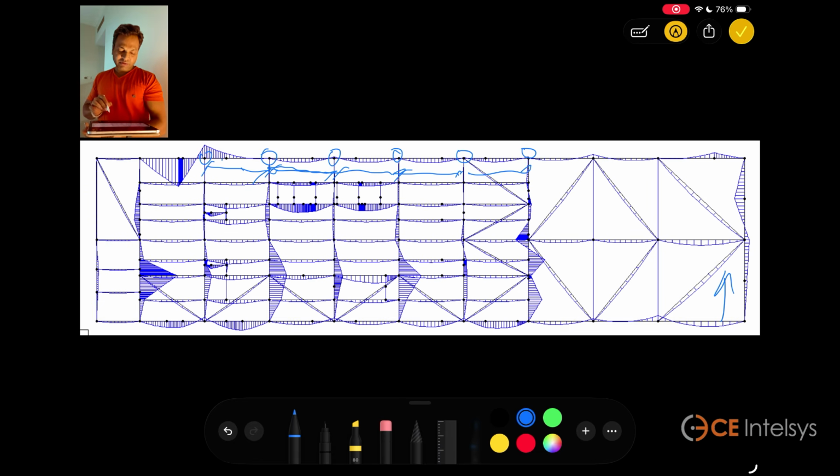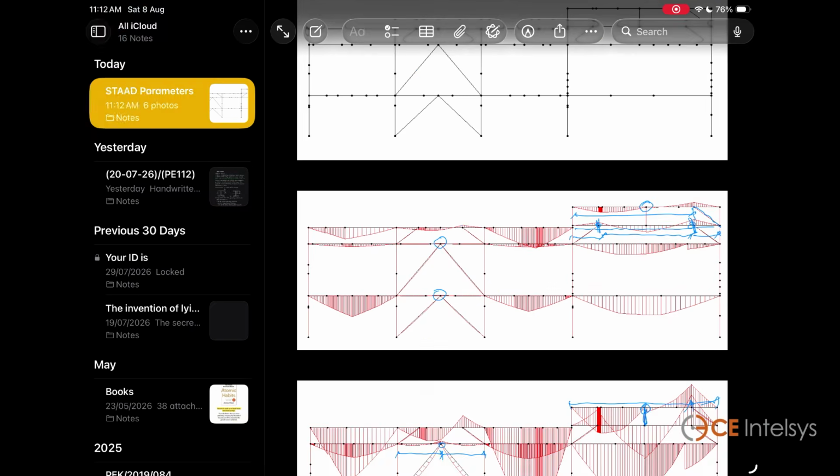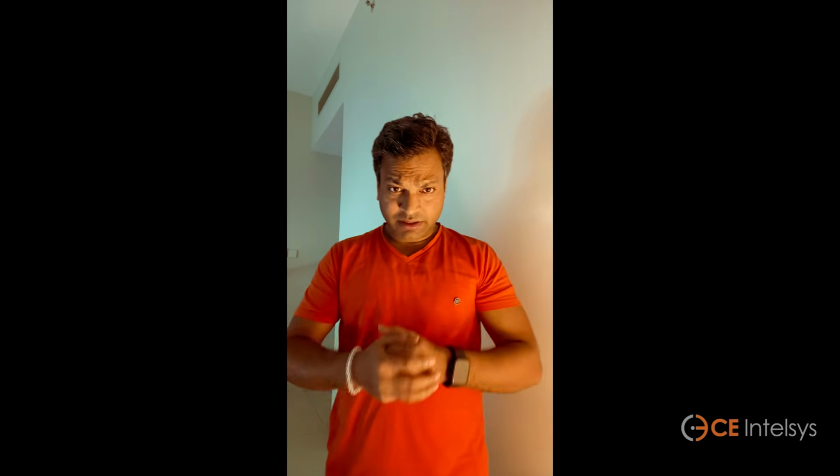So application of the self-weight in the respective direction will help me to analyze the bending moment diagram and define where my beam is breaking just because of the bending moment pattern. This very rational method can be used in complex bracing patterns to define the LY or LZ. Once you understand this rational approach, you will never again depend on guesswork or someone's visual judgment. Hope I brought the clarity, right?